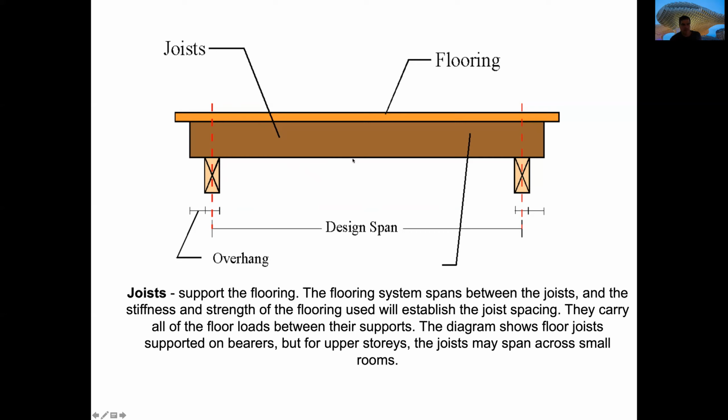Well, we already have a 3, and that will be in brown color here. And after, perpendicular to that, you need to have the main beams that are cut. Please do not represent it wrongly, with 2 lines, like a simple floor made out of concrete, next time that you are drawing a building made out of wood.